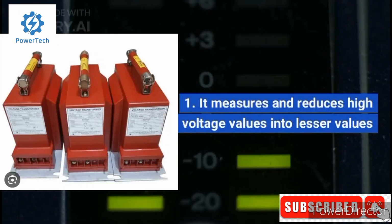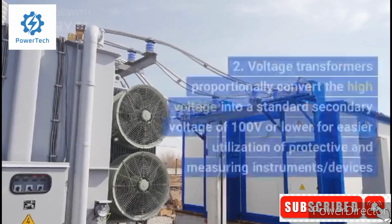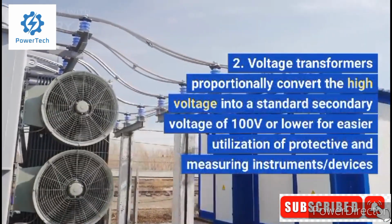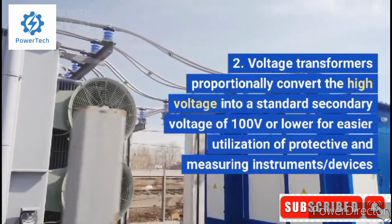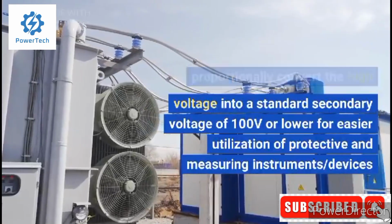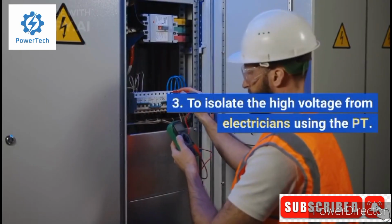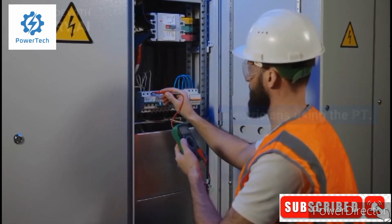It measures and reduces high voltage values into lesser values. 2. Voltage transformers proportionally convert the high voltage into a standard secondary voltage of 100 volts or lower for easier utilization of protective and measuring instruments, devices. 3. To isolate the high voltage from electricians using the PT.